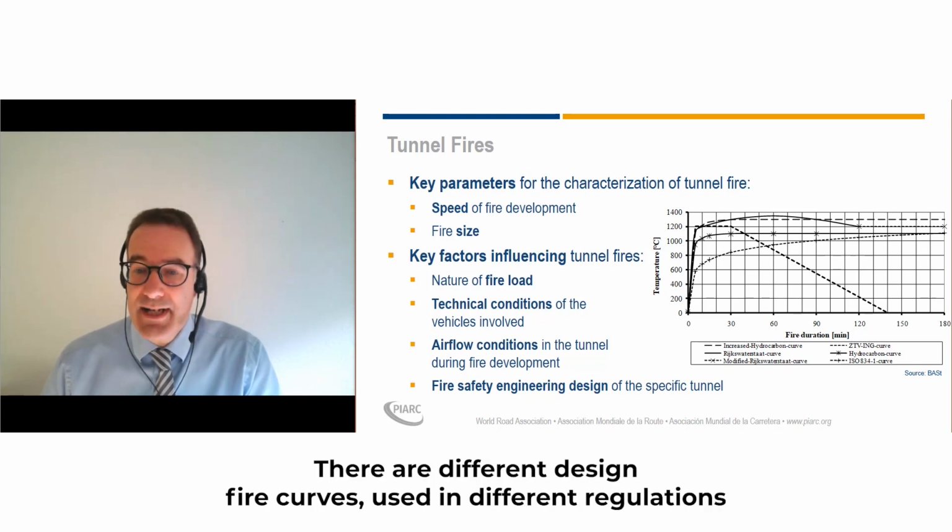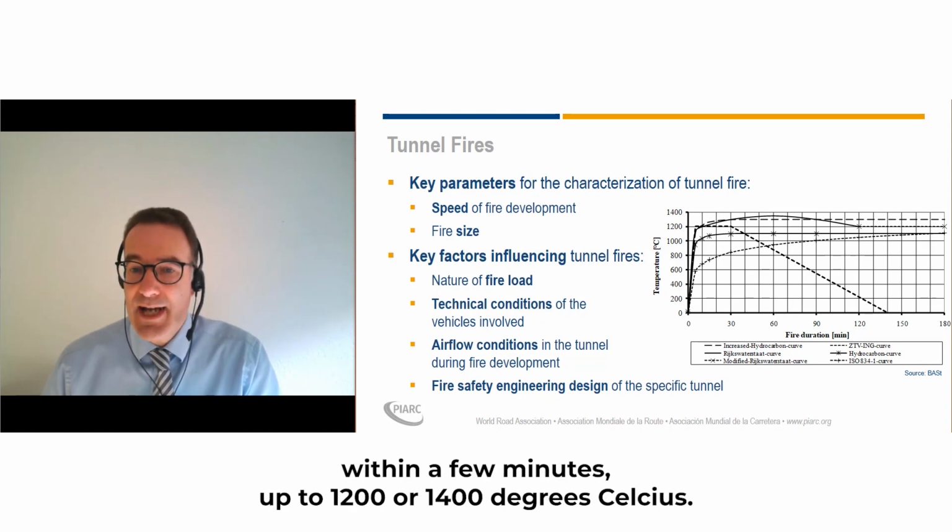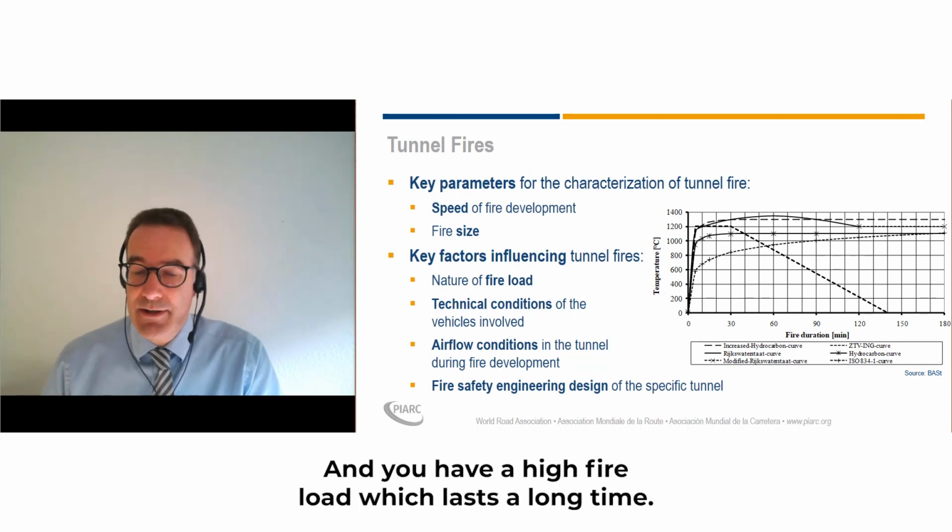There are different design fire curves used in different regulations. On national level, you can see all the fire curves include a very steep increase of the temperature within a few minutes up to 1200 or 1400 degrees Celsius. And you have a high fire load which lasts a long time.